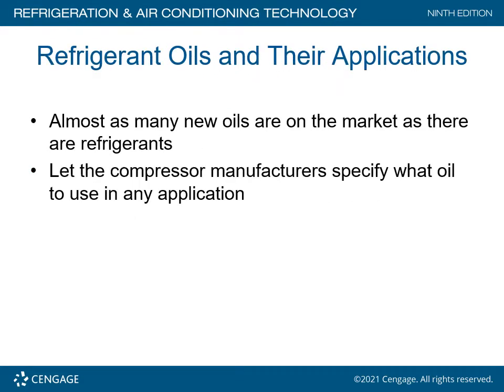Refrigerant oils and their applications. Almost as many new oils are on the market as there are refrigerants. Let the compressor manufacturers specify what oils be used in the application. I can tell you pretty much 95% of everything you're going to install in refrigeration and air conditioning today contains POE oil.